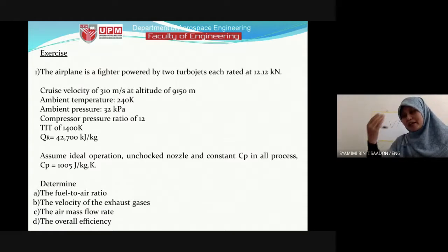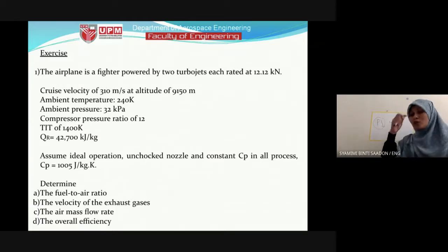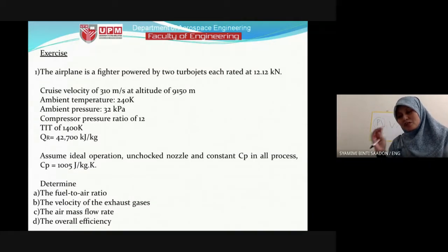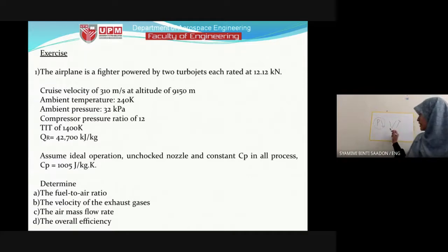So the fluid will enter the Venturi tube, or the nozzle in the engine. The air will keep entering the nozzle, the velocity increasing, and the mass flow rate also will increase. But only up to some point, which is the critical point, where if we keep decreasing the back pressure, the mass flow rate of the fluid will not increase anymore.